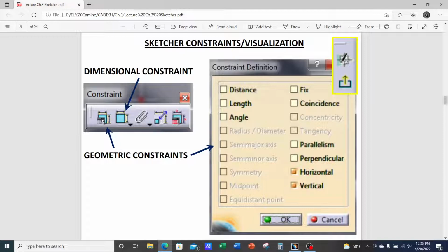If you want to add geometric constraints, in other words, you want to add a relationship between existing geometry, so if you want to add perpendicularity, parallelism between two lines, or you want to add coincidence, you first pre-select the geometry, click on this first icon, and then it'll give you an option of what relationships are allowed to add to those pair or more pieces of geometry.